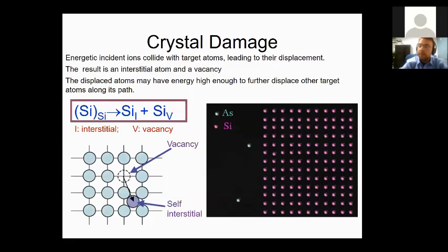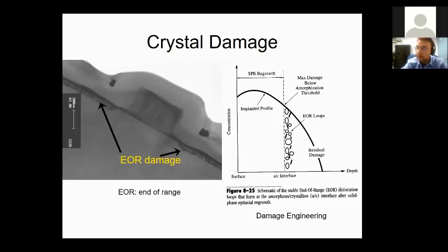Okay, so in this animation, we're seeing the propagation of the arsenic in the crystal. We are creating these self-interstitials, and we're also creating the vacancy defects. And at some point, the arsenic will stop, so that's going to be bringing another zero-dimensional defect too.